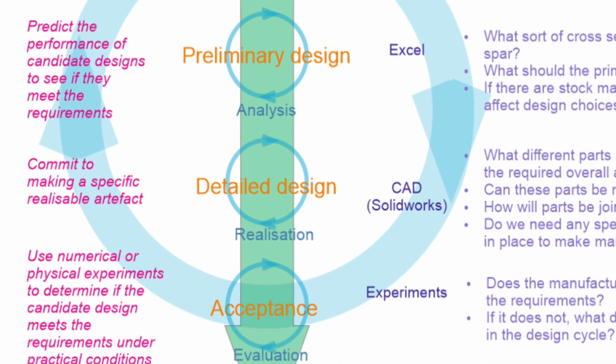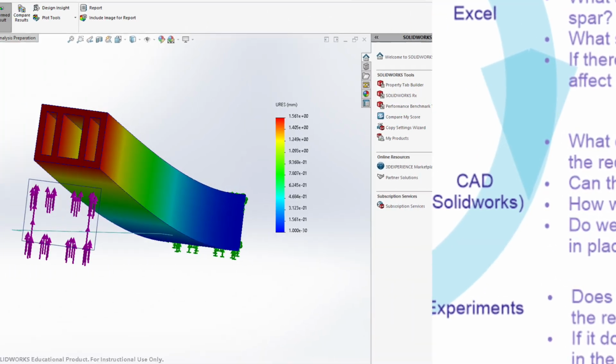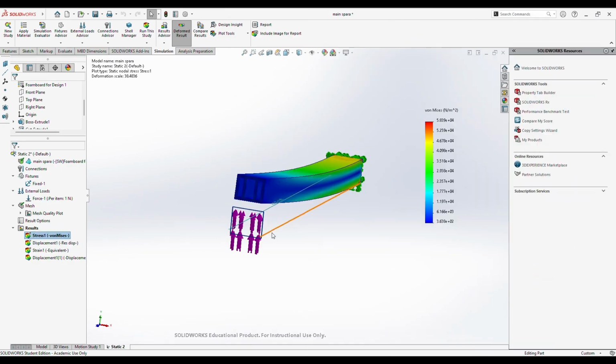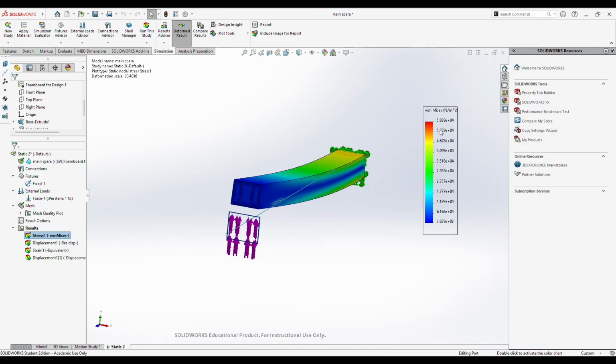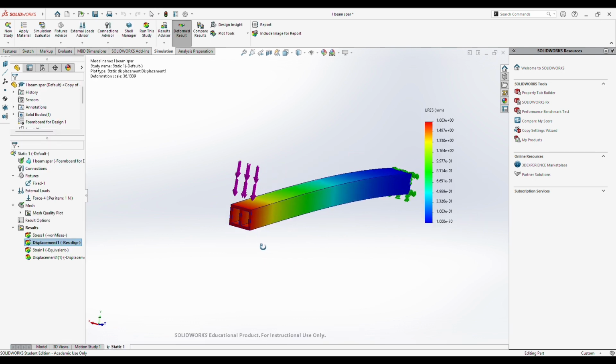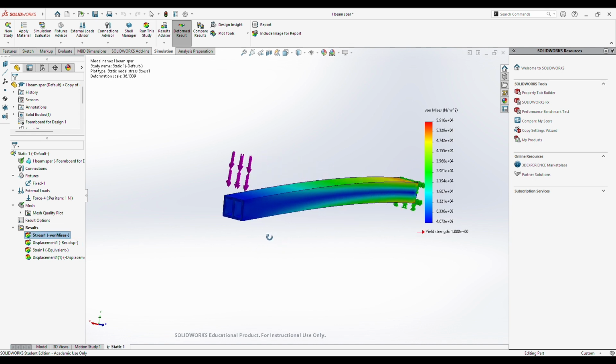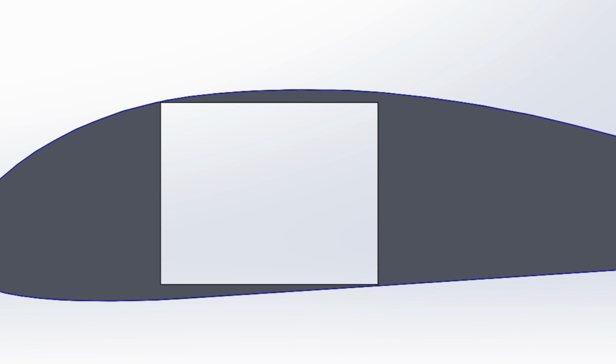We utilized SolidWorks to simulate loads and torsion on various spar designs. Using the data from the spreadsheet, we found ideal dimensions for the spar and implemented it into a tapered I-beam and our current double I-beam spar. This provided the maximum displacement of the beam, as well as how the stress is distributed across it, as well as give us an insight into the mass of each spar.